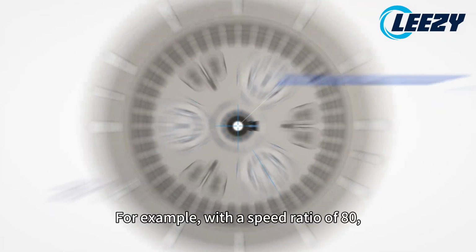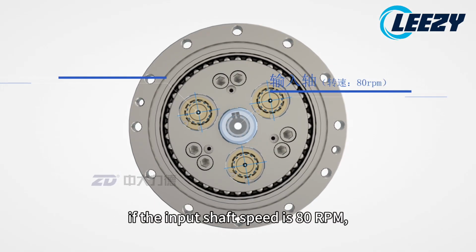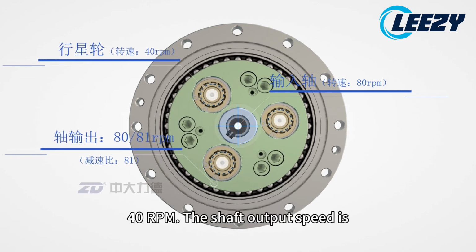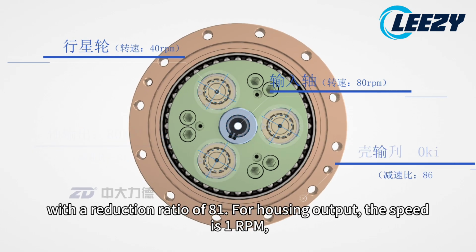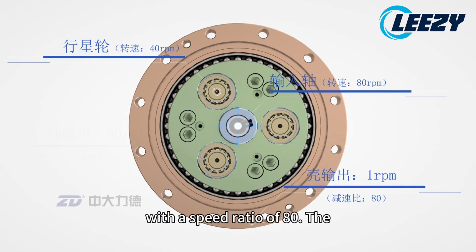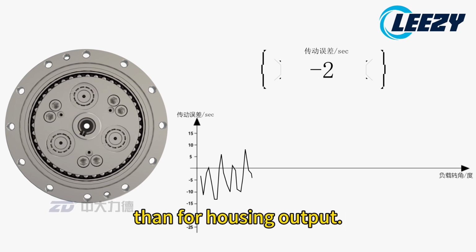For example, with a speed ratio of 80, if the input shaft speed is 80 RPM, the planetary gear speed is 40 RPM. The shaft output speed is 80 or 81 RPM with a reduction ratio of 81. For housing output, the speed is 1 RPM with a speed ratio of 80. The reduction ratio for shaft output is 1 higher than for housing output.